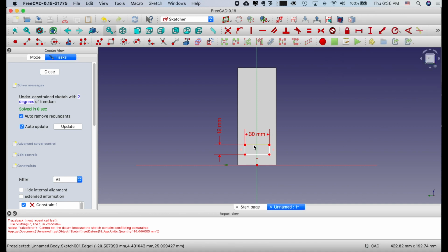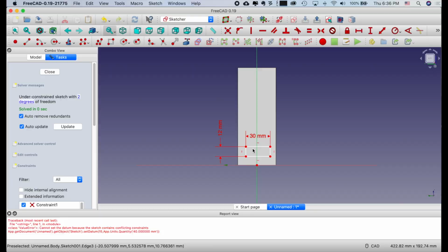We're good there. And now this is great, except it's not locked in place. So what I really want to do is find the edge of this drawing. But the edges of this drawing are not accessible to me because they're on another drawing. So I need to map them into my space. The way you do that is you look here for this little icon that looks like a plunger on dynamite. And you go down to the edge that you want to map and you click on it.